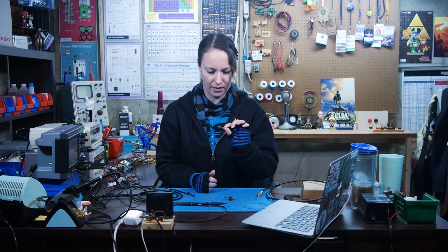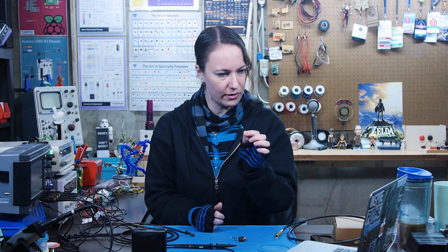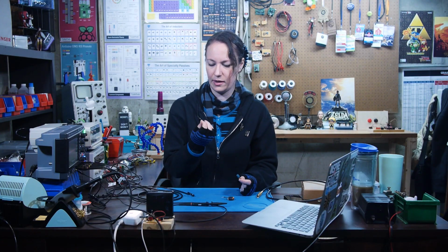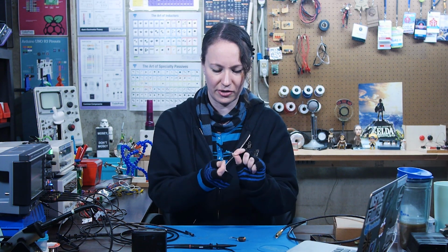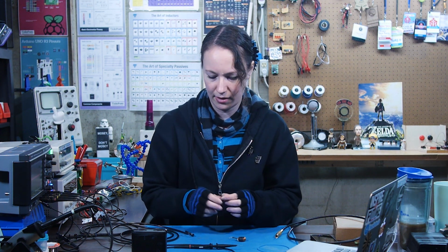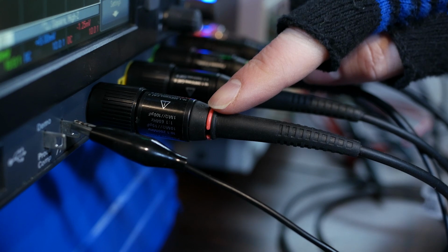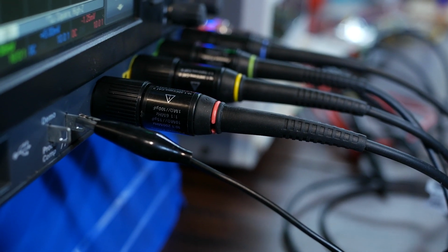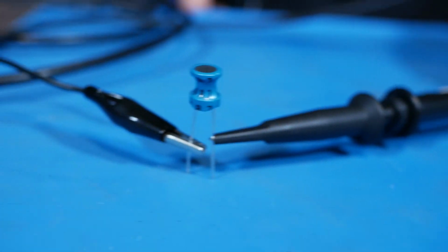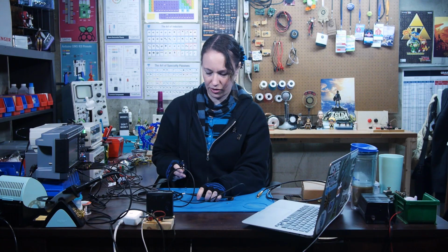So I've got a 4.7 radial lead, it's a ferrite core, or iron core. So this is non-shielded. And then I've got one of the SMD metal composite shielded ones, obviously much smaller here. So I'll start with the bigger one, the non-shielded. My red probe here is connected to the function generator that is part of my oscilloscope. I'm going to connect the other end of the inductor to ground here.